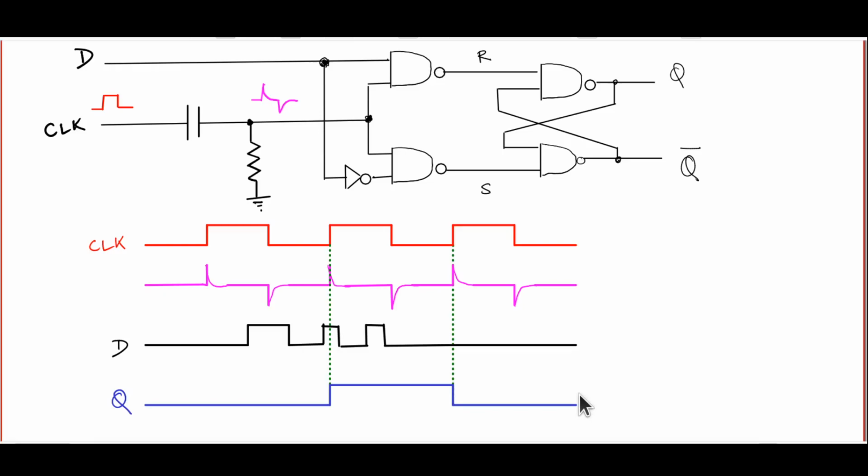So, whereas a capacitor is a pretty cheap discrete component, on an IC, a capacitor is very, very expensive. And you want to avoid it as much as possible. What are actually used in integrated circuits are much more complicated circuit combinations which effectively give you the same result of edge triggering, but without using an actual capacitor.